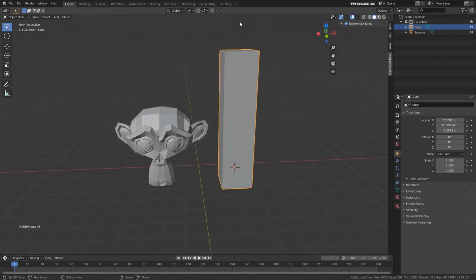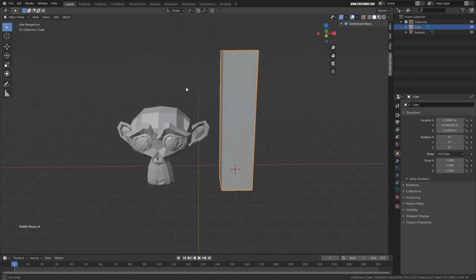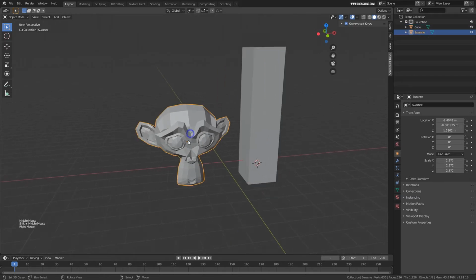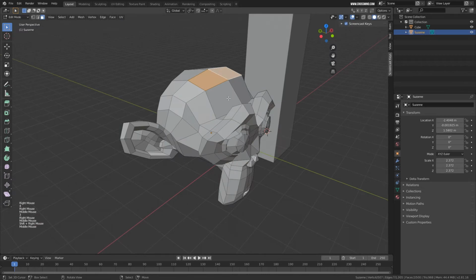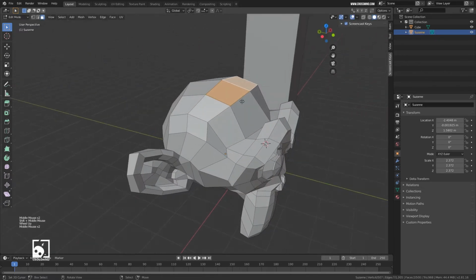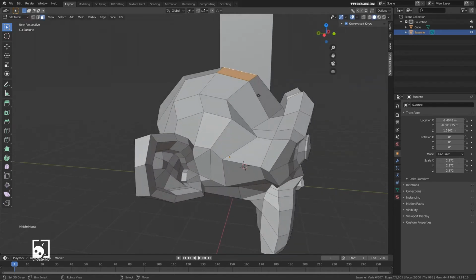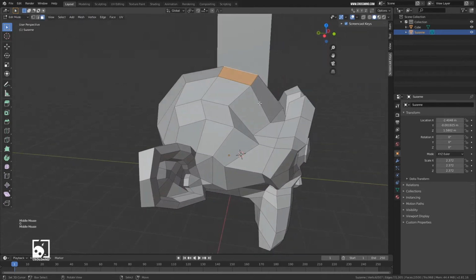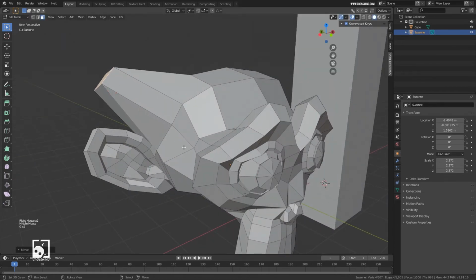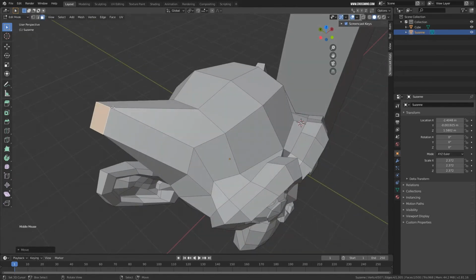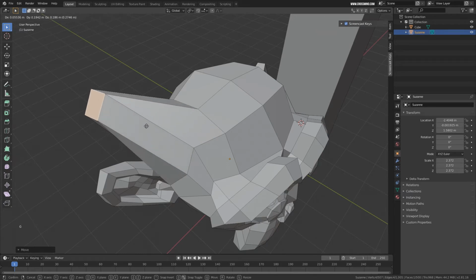Okay, so that we can have some smooth mesh over here. Now what proportionate editing does is, if you are coming from other software, this is like a soft selection. Now if I go over here and select any face or multiple faces and move them, these are like a hard selection. I mean these are creating some very hard deformation in my mesh. Now if I move this one, I have this weird looking result. I just want some smooth transition and not just to move one face.